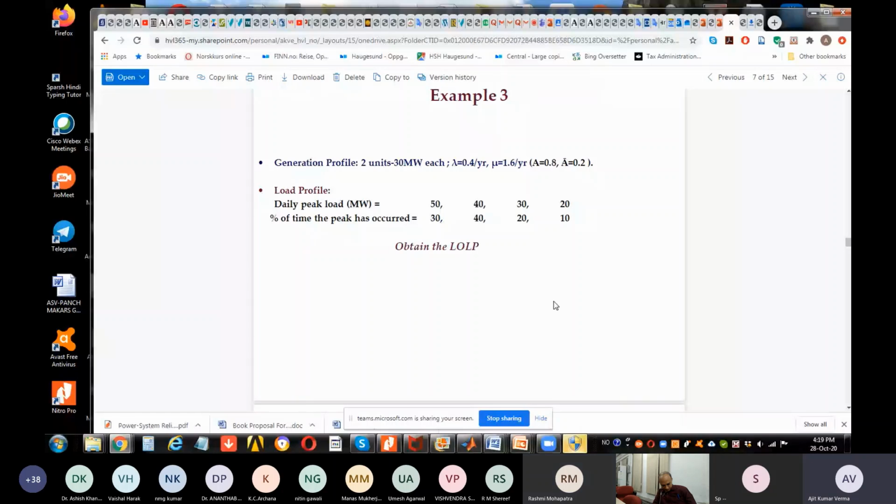Yeah. So basically, one thing is that we should know that it's a bottom-up approach. Unlike fault tree analysis, which is a top-down approach, this is a bottom-up approach. We are looking at the functional failures of components, units, subsystems, and system. And what is the impact that components, units and subsystems would have on the system failure? And what is their criticality? The criticality ranking is possible.